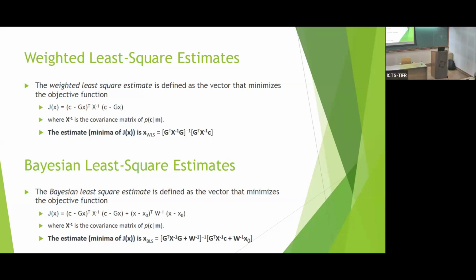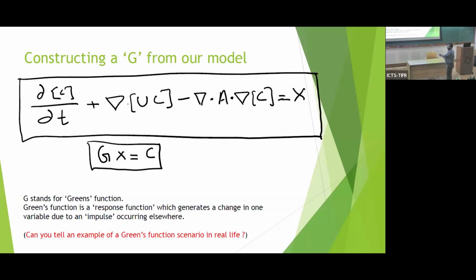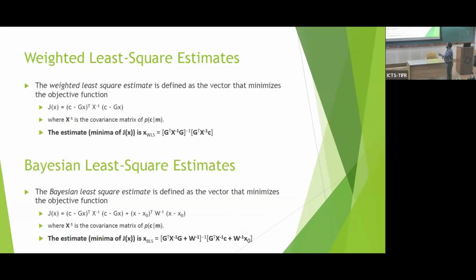No way, because the model you consider is so simplified. It has only two terms, advection and diffusion, but there are n number of natural processes out there which cause the actual observed C in your place. You are not having that in your model, therefore your C will never equal Gx. They are supposed to be the same as per the previous equation, the difference should be 0, but it will not be, right? Therefore, there is an error.